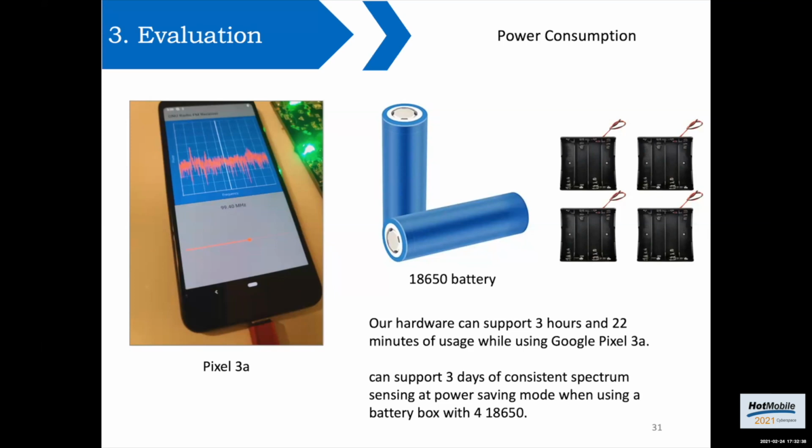The power saving mode is a mode in our firmware where you can turn off the transmitter of the front end to save power. So in spectrum sensing applications, you are always using the receiver only mode. This will save almost 50% of power consumption.